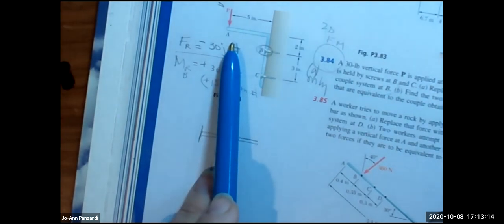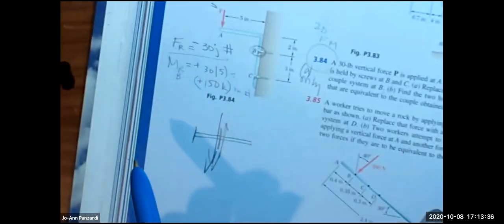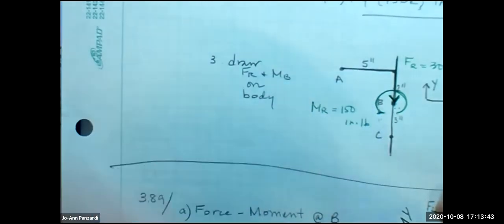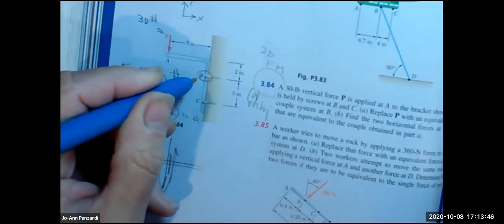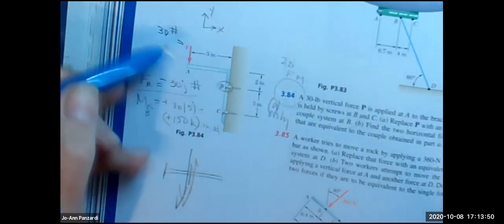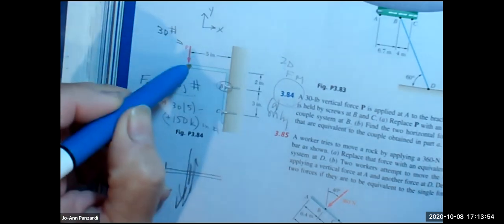I think what Jason's question is, is that those things seem different. He's saying pushing out at A is different than pushing down at B. But the way Maria said it helped me clarify it: pushing down at A is equivalent to pushing and twisting at B. Correct. Because point B is the point in question. What is point B experiencing with this 30-pound force? If it was a free body, this whole bracket would start moving down due to that 30 pounds, and it would also twist due to that 30 pounds.